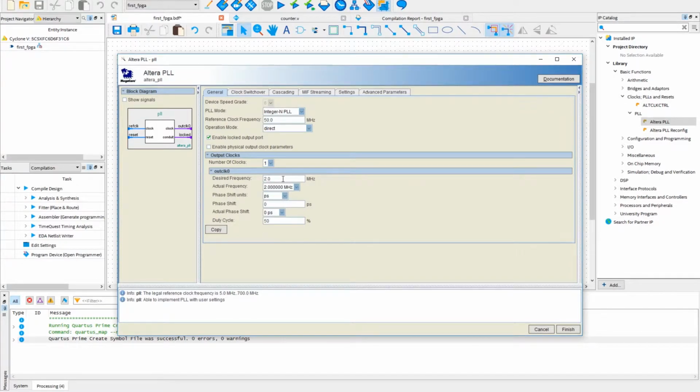For example, if I want to have 1 megahertz, the PLL will tell me that's impossible. You can generate a minimum of 1.17 megahertz, so that's not going to be possible to get exactly 1 megahertz. But for another frequency, if you can generate it, you can just choose the number that's bang on. But if you have to choose a number that's not really bang on, then you have to choose one that you think fits your feature need the best. And I don't really care about the log output, so that will be it.